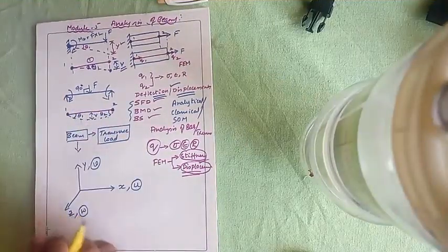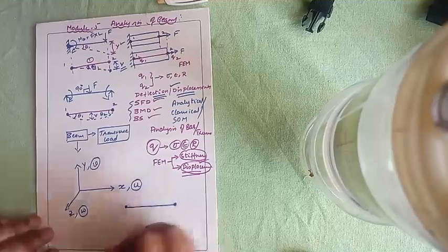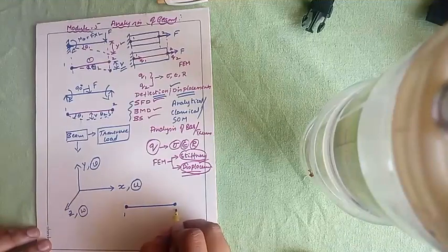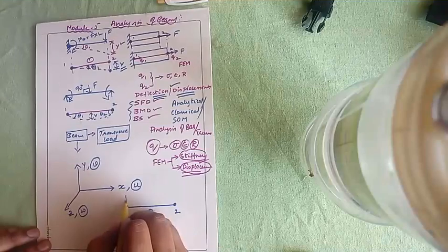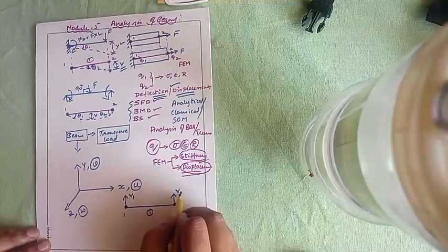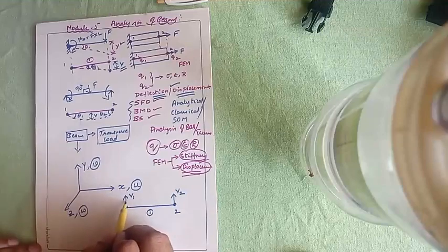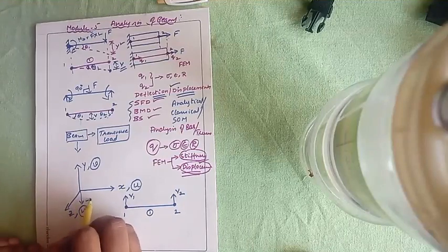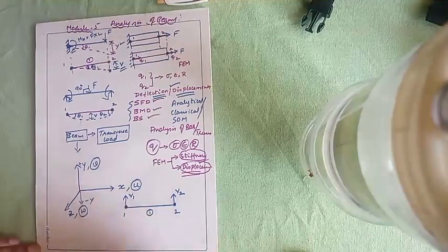So this is the basic of a beam. Now, how exactly do we represent a beam in FEM? If this is a beam element, this is node number 1 and this is node number 2, and this is element number 1. Each node will have a linear displacement, indicated by the upward arrowheads V1 and V2. That is the sign convention we want to take. Since positive y is upward and downward is negative y, to show the positive sign convention we show the displacements in the upward direction.